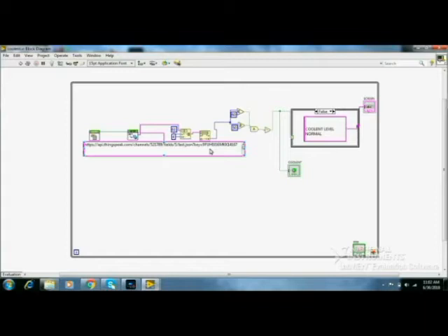Here, the temperature from the suction line is stored in field 5 of fan issues in our ThingSpeak channel, and we retrieve that value and check whether the temperature is between 50 degrees Fahrenheit and 60 degrees Fahrenheit. If the value exceeds that, then we will print the alert message that the coolant level is not normal. Consult a technician. Now let's see how this works.